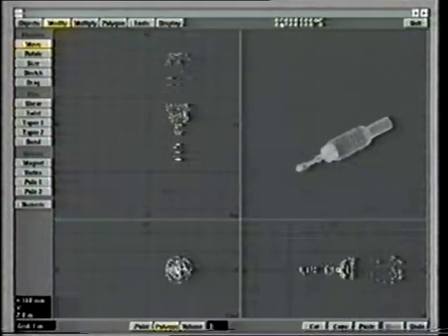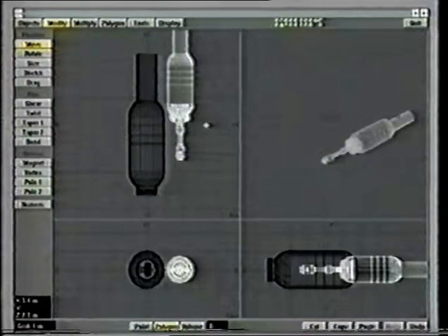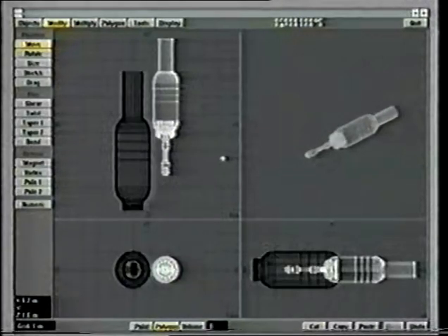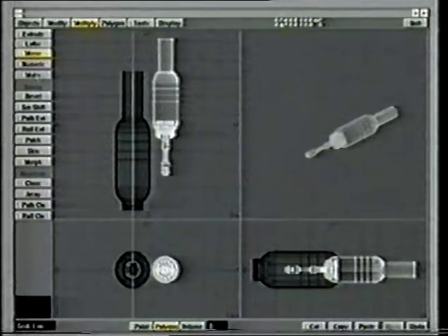Okay, still need a little bit more clearance. Okay, that's around about where I'm going to want it. Let's center everything up. Okay, so all the gun surface names on this will retain, and then we'll create a second set of surface names for the other gun. So we'll use multiply, mirror, set the mirror up in the middle, make.